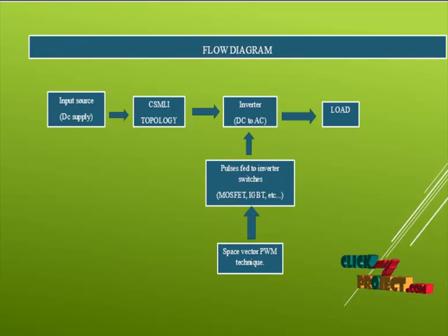Next we see about the flow diagram. In this proposed work we overcome the drawbacks of the existing system and compare the result with the existing method. The proposed circuit is named as the basic unit and contains two DC power supplies, two capacitors, two passive power diodes, four active power switches and six MOSFET switches. Input sources such as photovoltaic cells, batteries and fuel cells can be used as a power supply in this structure. Switches SA and SB are used in series parallel conversion respectively.